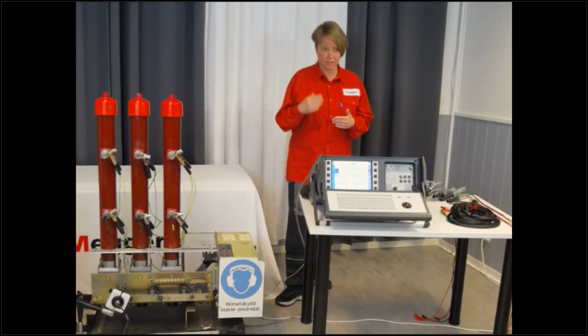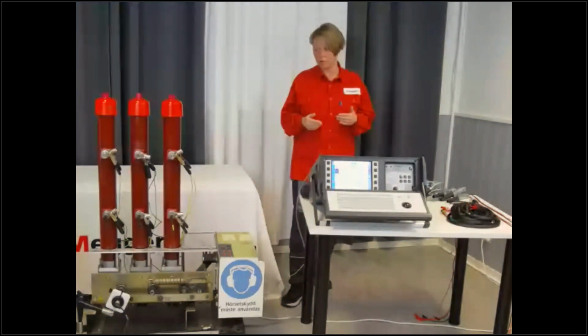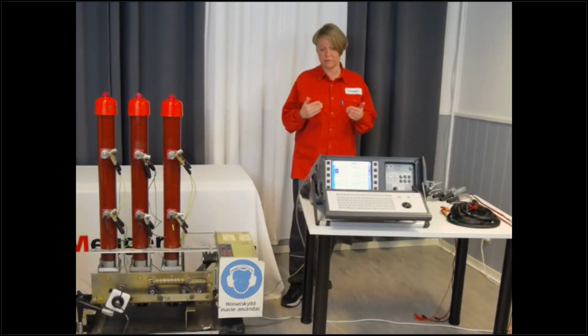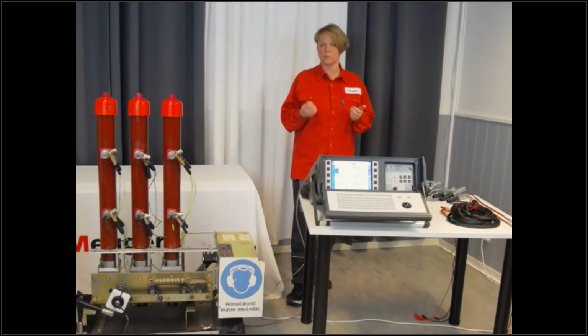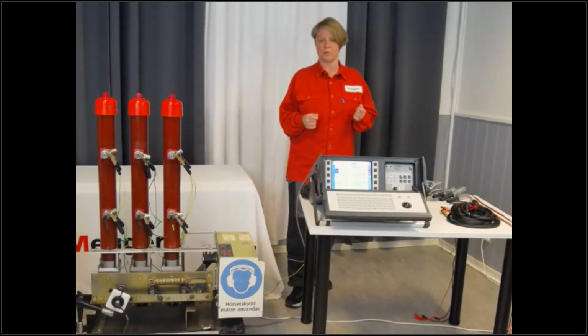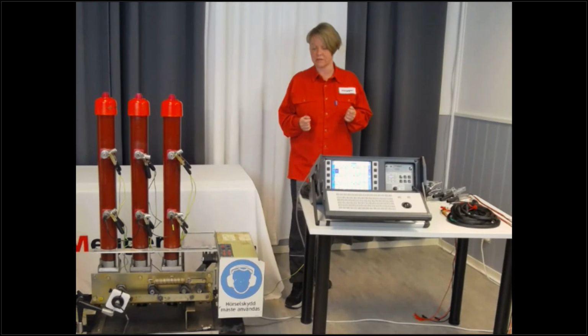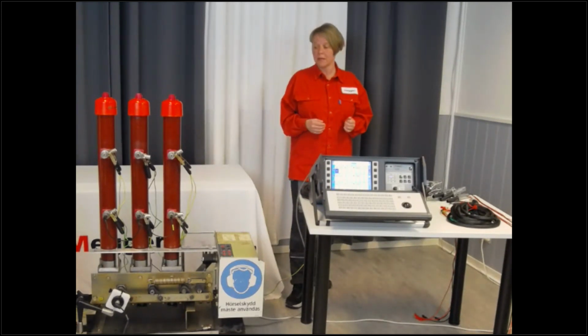I was doing a demo in Spain a few years ago where we had this kind of situation, where we only had this kind of grounding device. And what we did was that we used ferrites to separate the grounds instead. So we put ferrites on the grounding device. So that was one way of overcoming it.